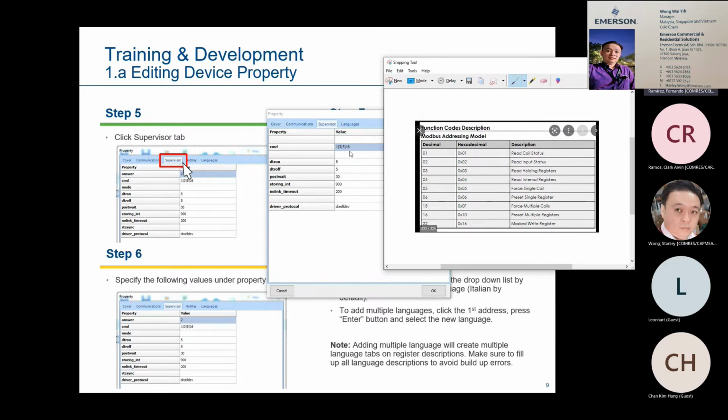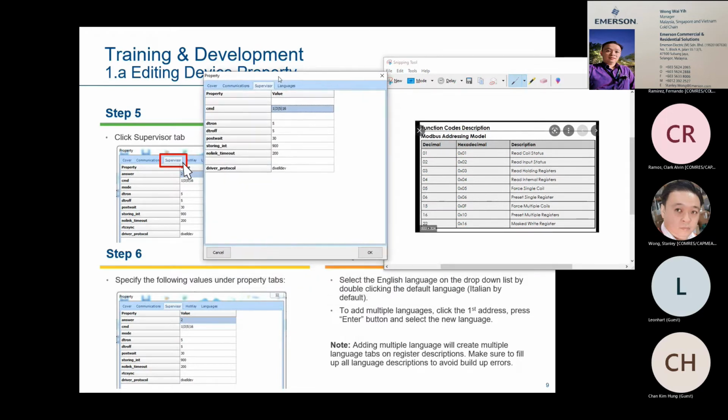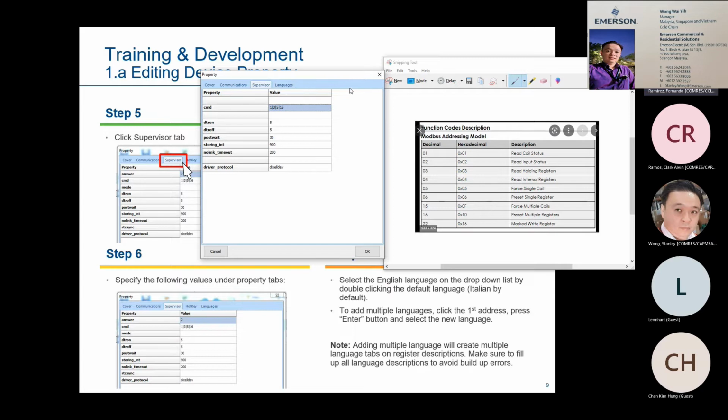So these are very common Modbus commands used by Dixell, but some third-party devices might use input registers or input statuses. So the first 2 digits might change. Normally, the third and fourth values are universal because only digital coils can be written or configured, as well as analog holding registers.